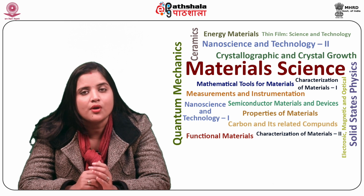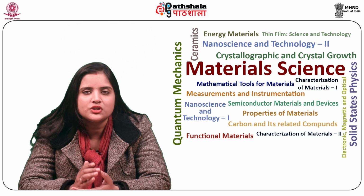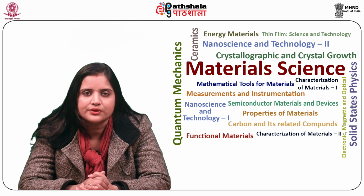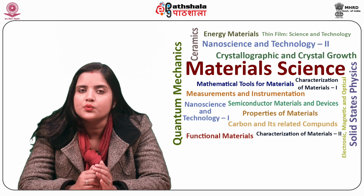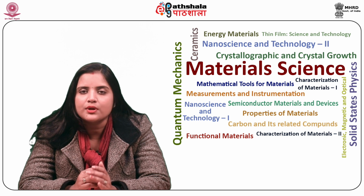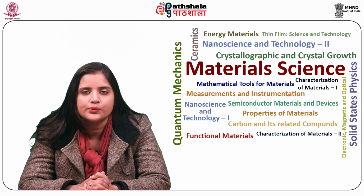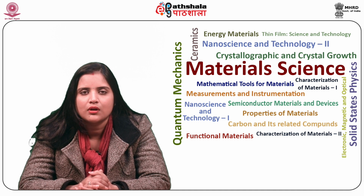Vapor deposition processing includes techniques which deposit materials in a vapor state by condensation process, chemical reactions, or certain types of conversion processes. The deposition process is known as physical vapor deposition if a liquid or solid source is used to create the vapor phase.